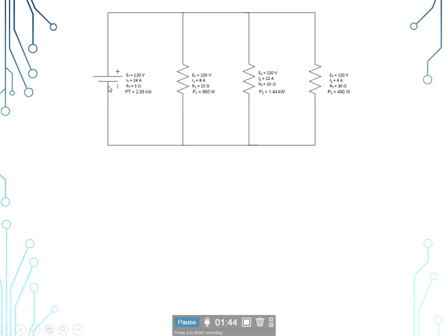The way that we tell that it's a parallel circuit is we trace this circuit. We have one path up to this point right here. That point is called a node. That's where 2 or more wires are joined together. So we have a path here or we have a path here. We come to another node, so we have 2 more paths, one up there, one up here. And then we go through our last load and come back. They all join together with another node, full circle back to the power source. In a series circuit, we call them series strings. In parallel circuits, we call them parallel branches, and this is a 3-branch parallel circuit.